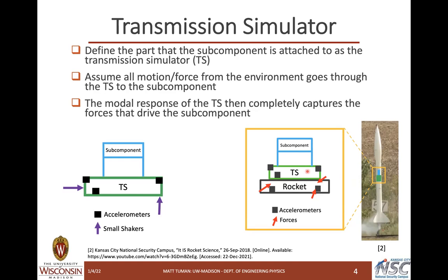And because the subcomponent is only attached to the transmission simulator, we can assume that force from the environment goes through the transmission simulator to the subcomponent. And if this assumption is correct, the response of the subcomponent should be completely dependent on the response of the transmission simulator. This means that even if we detach the transmission simulator and the subcomponent from the complete structure, if the modal response of the transmission simulator from operation is accurately reconstructed, the subcomponent response should also match its environmental response.